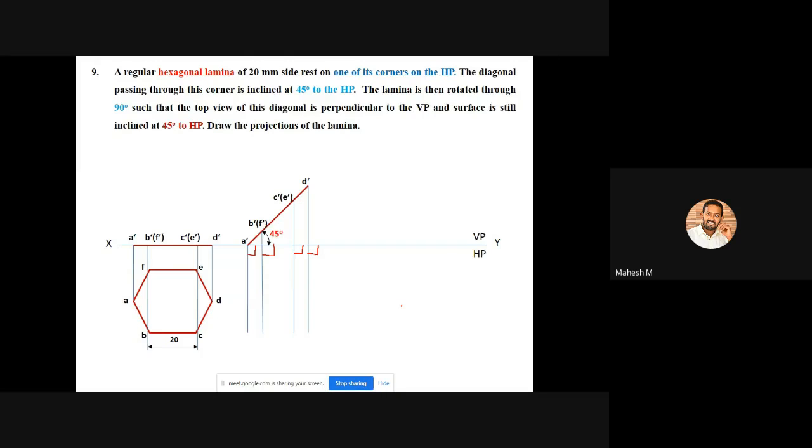If the angle is not 90 degrees, your final diagram will be wrong, so it is compulsory. And also with that, you can project the points that are available in the first top view towards the second top view position. That means you can project these 3 points like this.